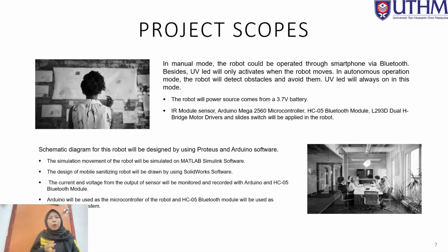The robot's power source comes from a 3.7 volt battery, and it uses an IR module sensor, Arduino Mega 2560 as microcontroller, an HC05 Bluetooth module, an L293D dual H-bridge motor driver, and a slide switch. The schematic diagram for this robot will be designed using Proteus and Arduino software. The movement of the robot will be simulated on MATLAB simulation software.